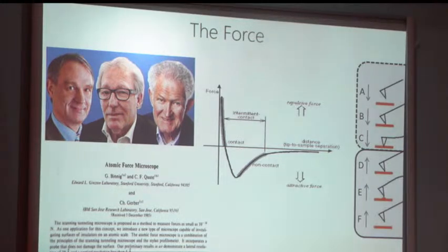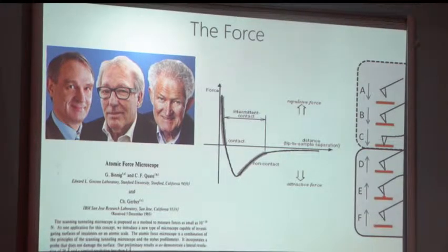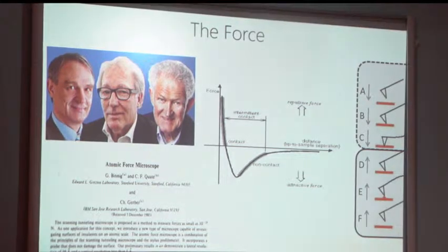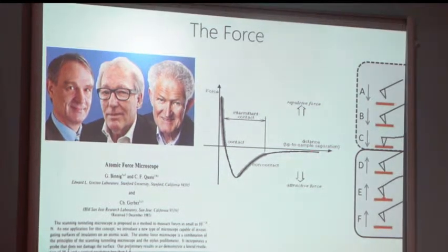And force exists practically on any kind of substance, whether it is conductive, whether it is non-conductive, whether it is insulating, it does not matter. Force exists on every kind of samples. So when your sample and your sharp probe is far away from each other, there is practically no force acting on it. When the probe comes very close to the sample, let's say a distance between 2 to 10 nanometer, you will have forces starting to act on it, and these forces are all attractive in nature.